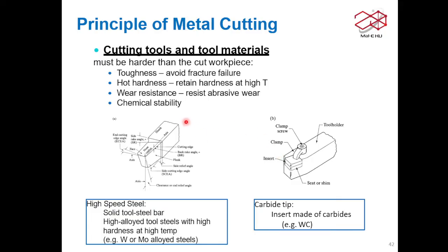For example, the high-speed steel bits, you might produce the whole cutting bit in one piece, right? The whole of the cutting bit is produced using high-speed steel because it's quite tough. It can withstand vibration quite well. But carbide bits or ceramic bits are quite brittle, so you don't want the whole piece to be made from ceramics or carbide or diamond.